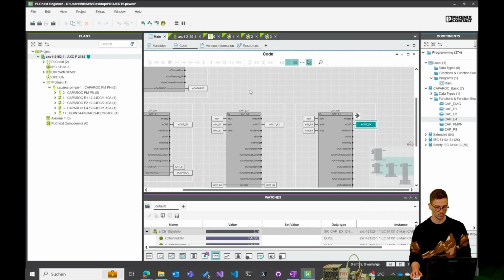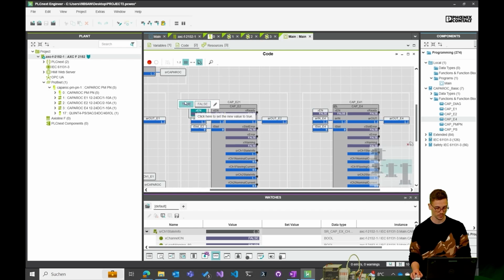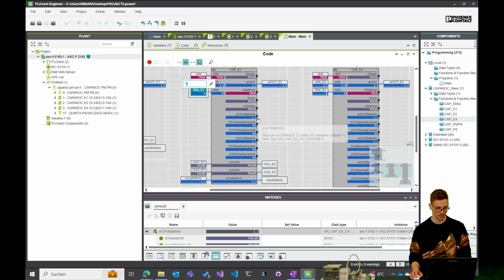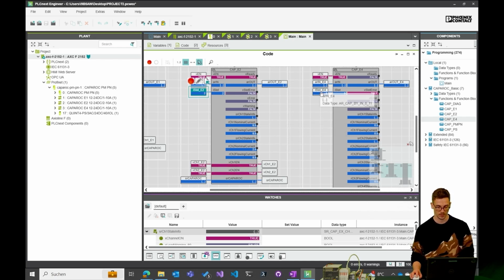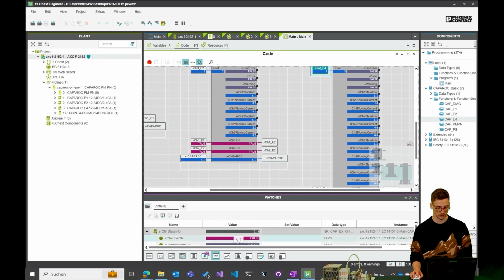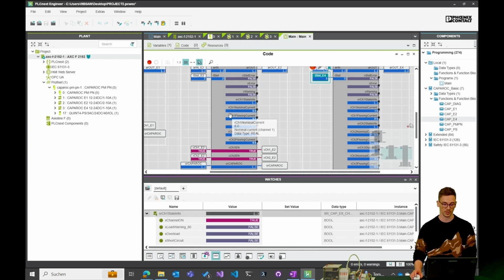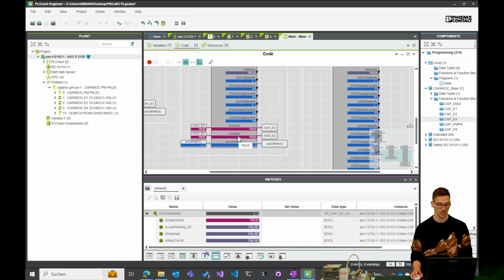Go into our main page. Go into the live online view. Slot error, because I don't have init values here, so we're using 2. We're using 3. So now it's ready. And you can see here that channel on is true, and because the devices are retrieving data from the function block again, I can also enable and disable the channels here over the function block.